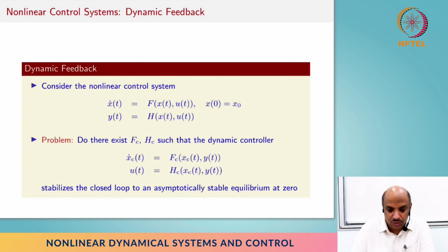And in fact, Kalman's filter plus regulator put together gives you the LQG controller. And the fact that these two things can be separated has a very appropriate name, it's called the separation principle. And then the idea of separation principle is used in nonlinear systems, where you have some kind of estimator part of it, and then use that as a feedback mechanism and treat it as a full state feedback design problem, and then both of them put together, right? But solving for stability is another aspect of it.